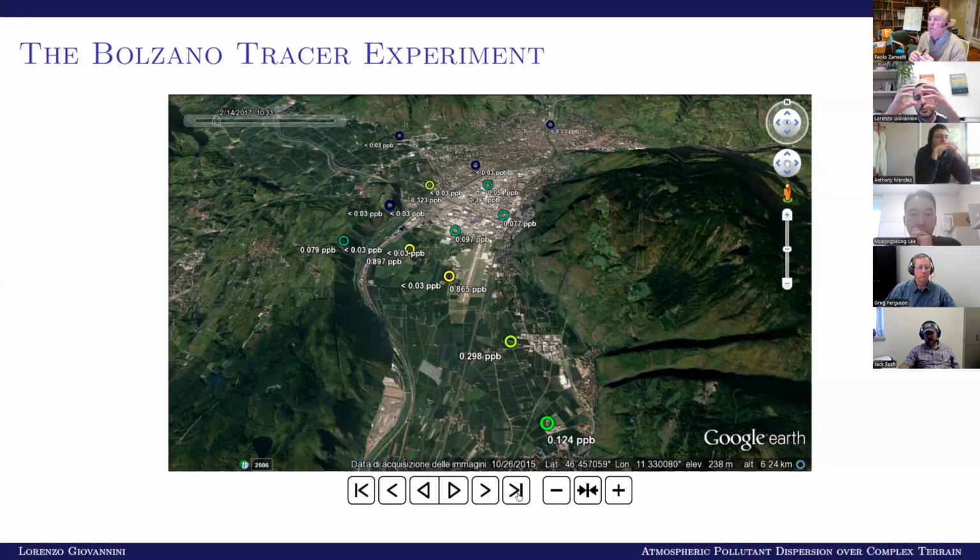In the morning, due to the strong stratification, the presence of ground concentration, the measurement of ground concentration, was delayed by more or less 2 hours after the release, because of course if we have a strong stable stratification, the pollutants which are emitted by the chimney, considering also the plume rise, remain confined at higher levels, and they are not able to reach the surface very easily.